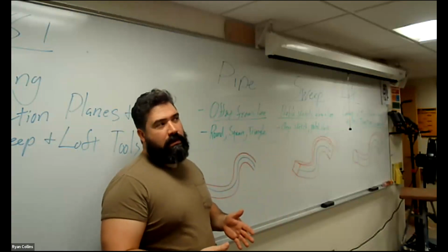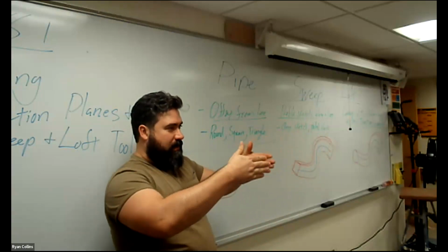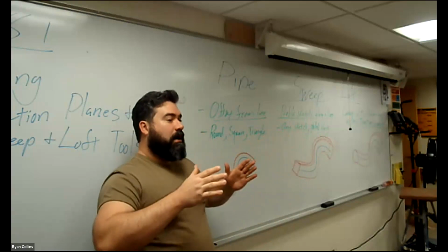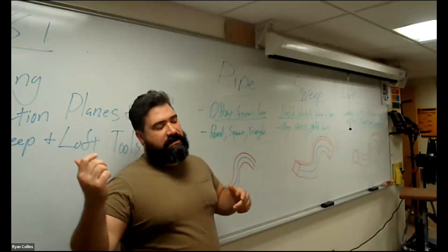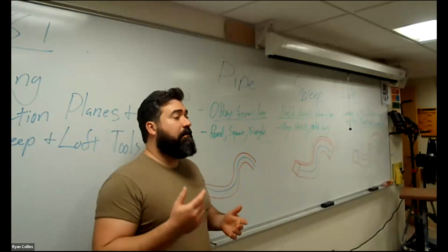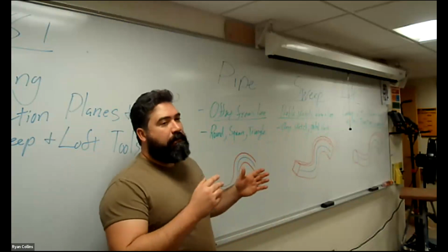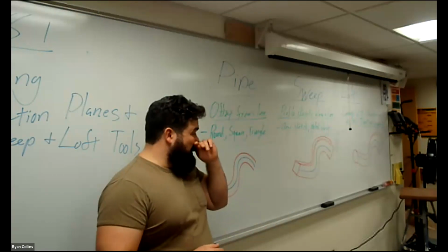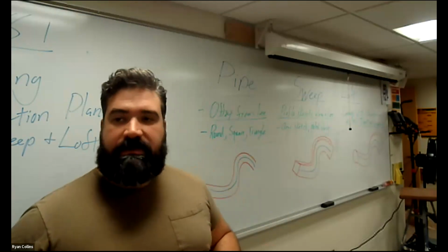the bow, the front, starts as a point, starts to sweep outward. I know I'm using similar terms. Curve outward along each of those ribs and ends at the flat back, unless it keeps going as a point. That's essentially how a loft can create more complex shapes. So it is for making more complex shapes based off of a series of profile sketches. So instead of just the amorphous term, let's actually look at Fusion here.